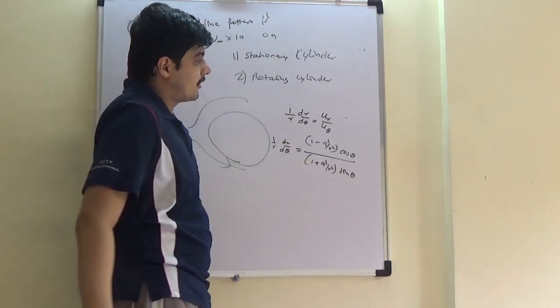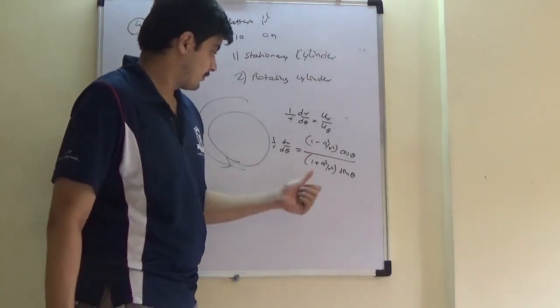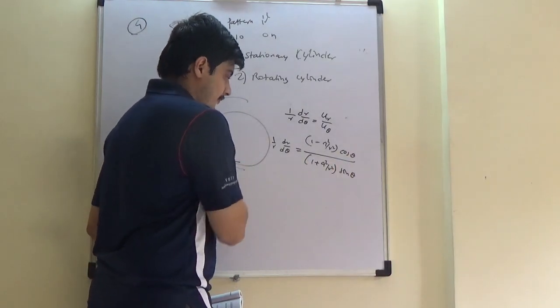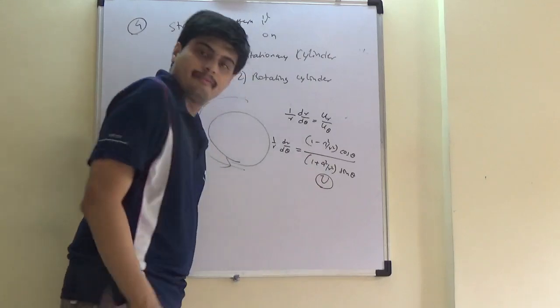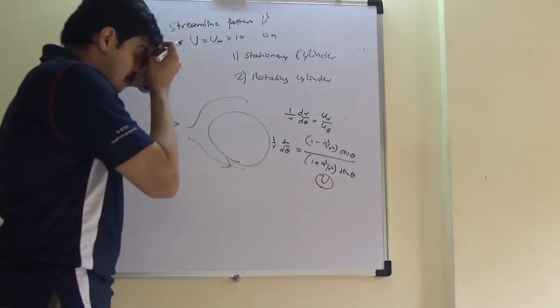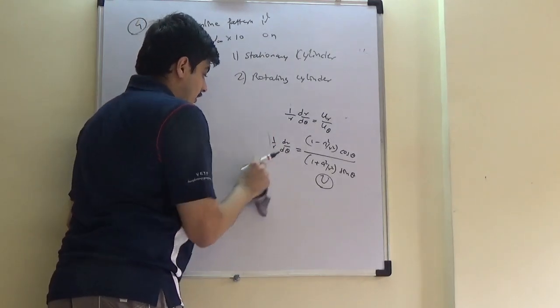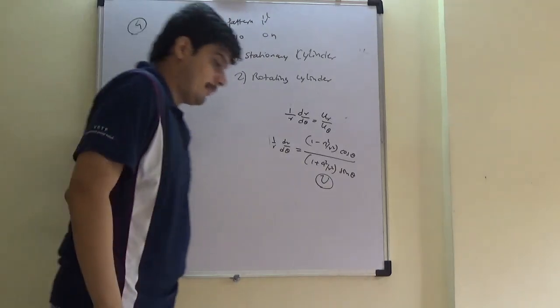So when the cylinder is stationary, ur is simply governed by this potential flow, u theta by this flow, right? Do you anywhere see a component of u here? No. Which means in the case of a stationary cylinder, velocity does not dictate streamline pattern, which is intuitive, right?